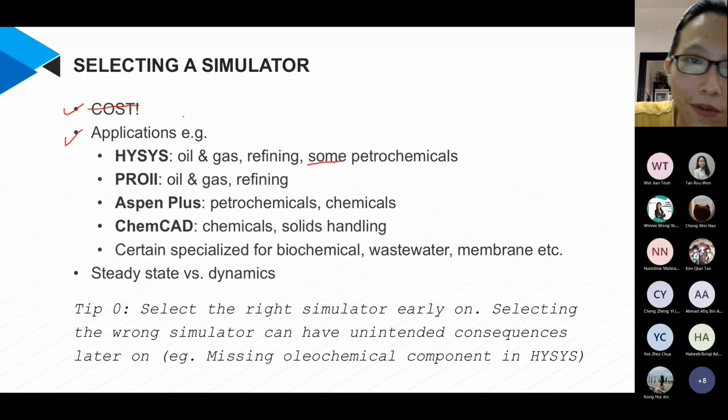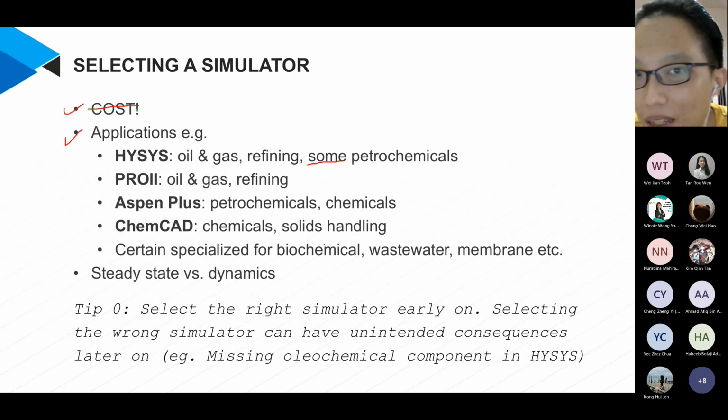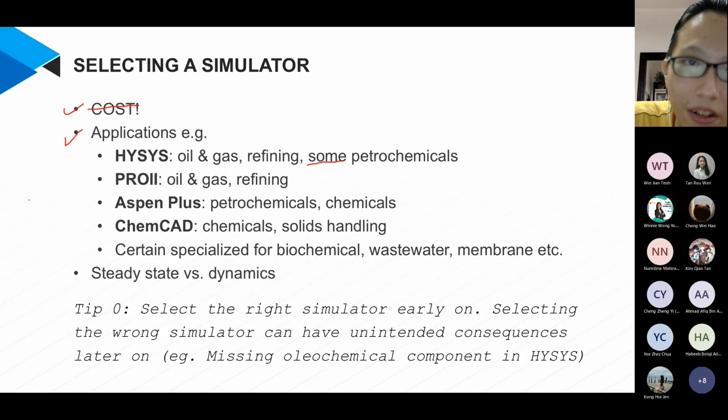If I have a biochemical process, can I use HYSYS? The answer is probably not, because HYSYS does not have the data for many of the components that you will use. So you need to make sure that you choose the correct simulator at the start before you even start doing your project.